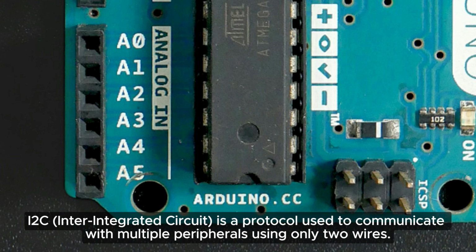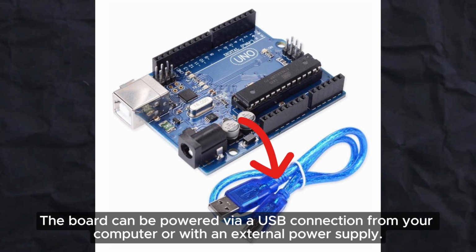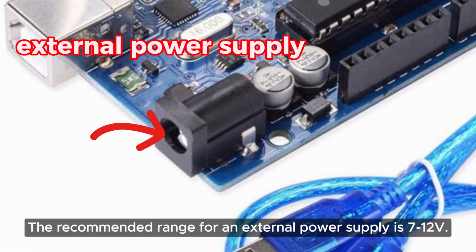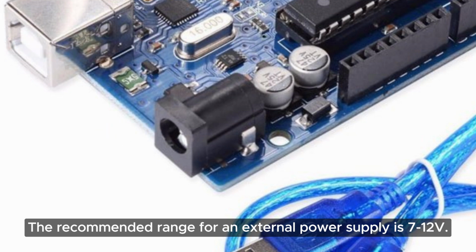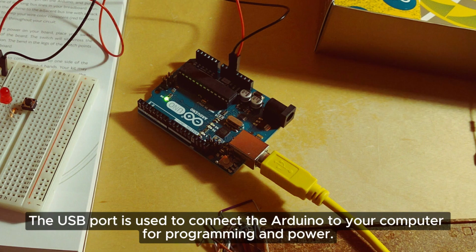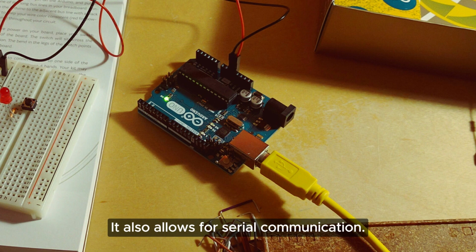The board can be powered via a USB connection from your computer or with an external power supply. The recommended range for an external power supply is 7 to 12 volts. The USB port is used to connect the Arduino to your computer for programming and power. It is also used for serial communications.